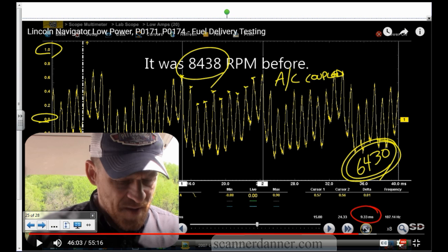What was wrong with the original pump? There was a mechanical problem with it. The original pump, based on these numbers, had a mechanical problem, not an electrical problem. My amperage was low because that impeller was damaged and either slipping or not pumping like it should. Maybe one of the fins were broken. It was allowed to spin a lot faster and not produce as much pressure that we needed. We can see that in these before and after numbers.